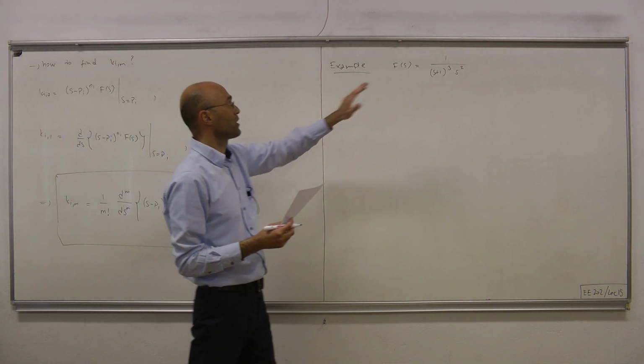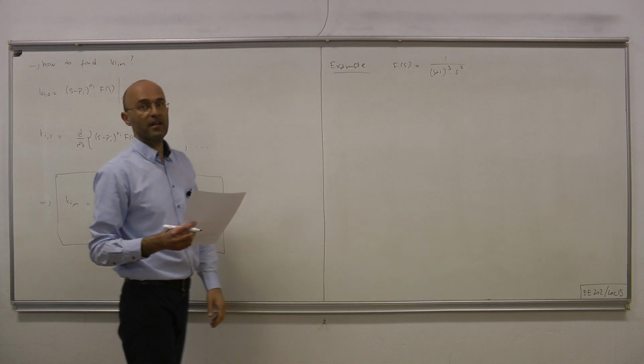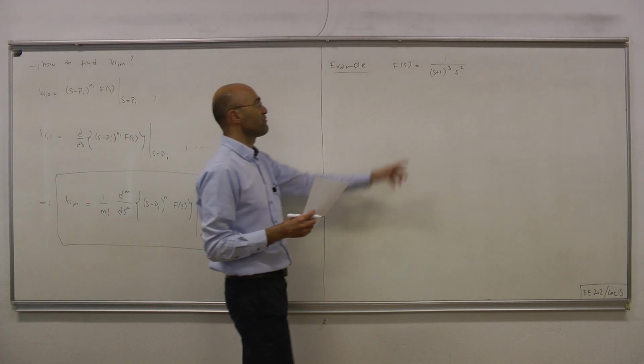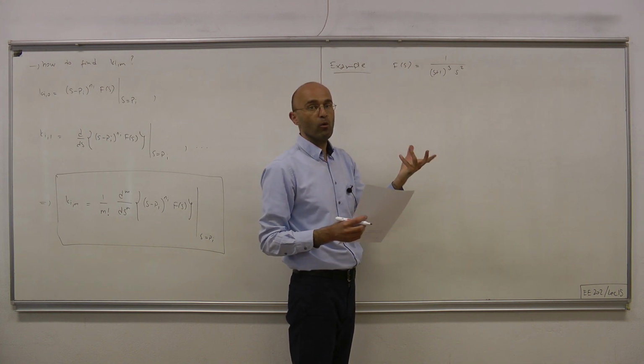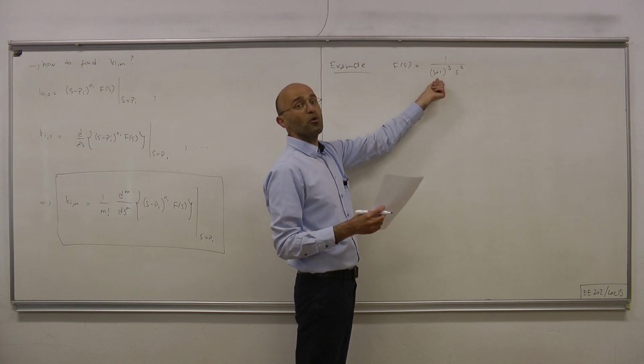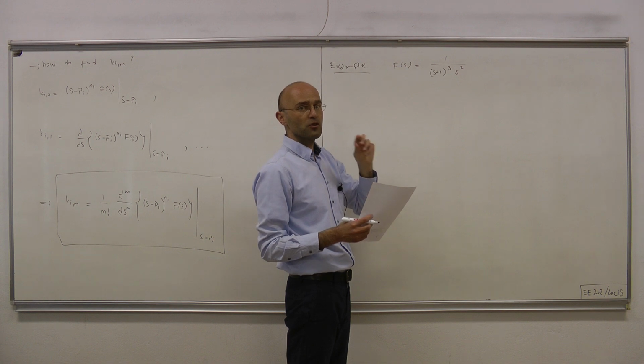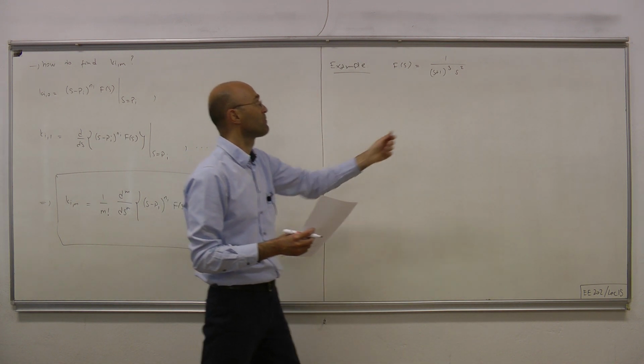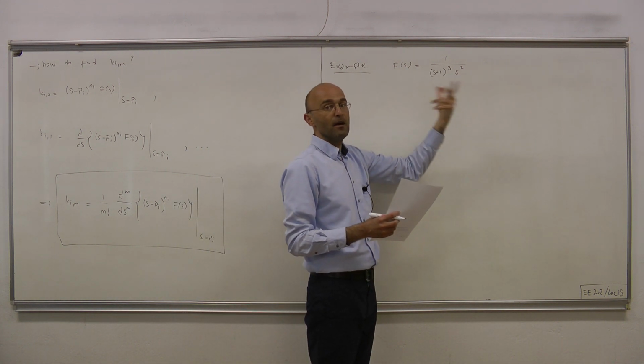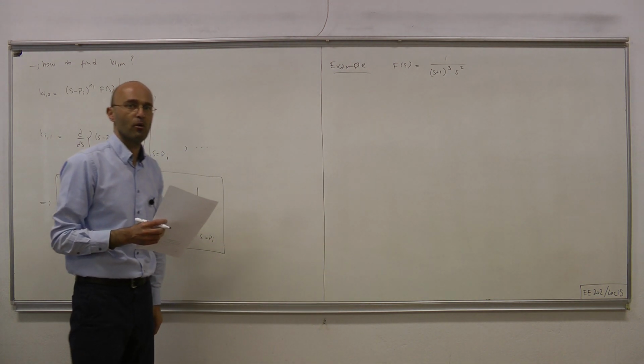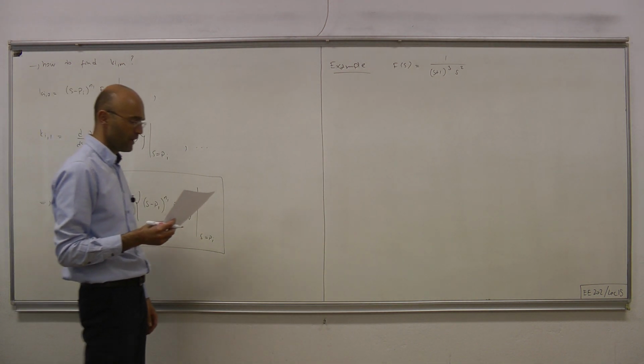Okay, so therefore we're talking about a fifth order case. So order 5 means we have 5 poles, and 3 of those poles are at -1, so we have a triple repetition at -1 and a double repetition at the origin, for the pole at s equals 0.